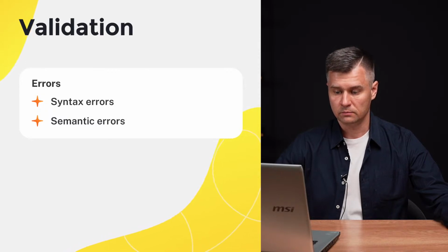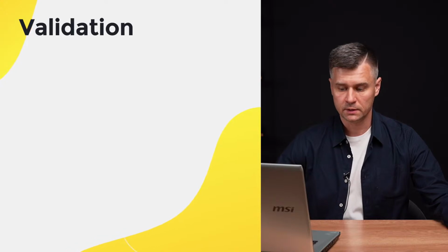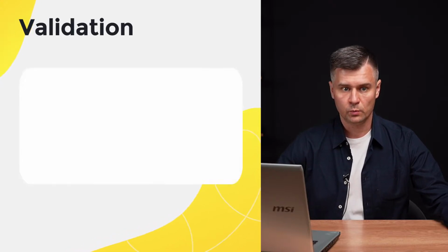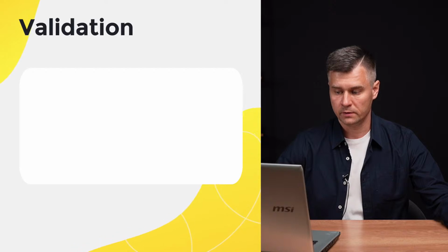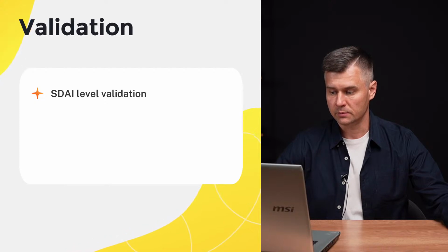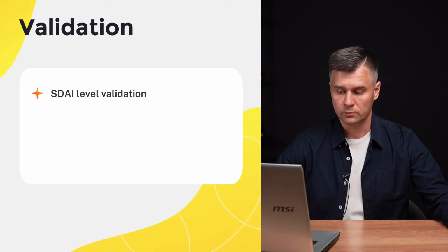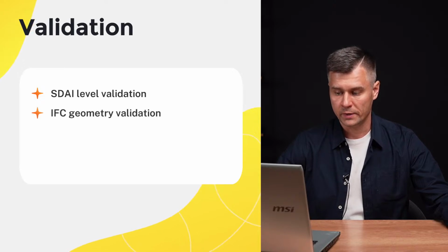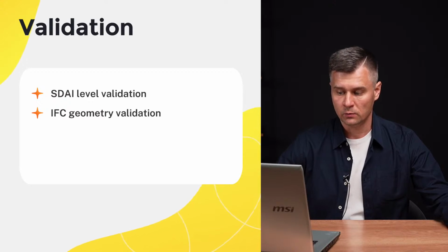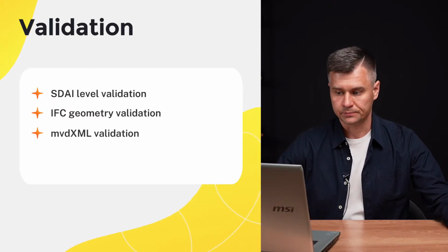This was about the syntax errors. But what to do with the semantic errors produced by various exporting applications? A huge part of the IFC SDK implementation is about different ways of semantic validation of models against rules defined within the EXPRESS schema for the format, the so-called interpretable where rules.